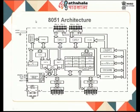That means for multiplication and division we will be using this particular register. Here we have memory, random access memory and read only memory, where we have all the special purpose registers. This is very important, as this may not look similar in other architectures. In this 8051 we have PCON, SCON, TMOD and the interrupt enable register. For assisting serial communication there is SBUF, and we have timer registers. So many registers are available.